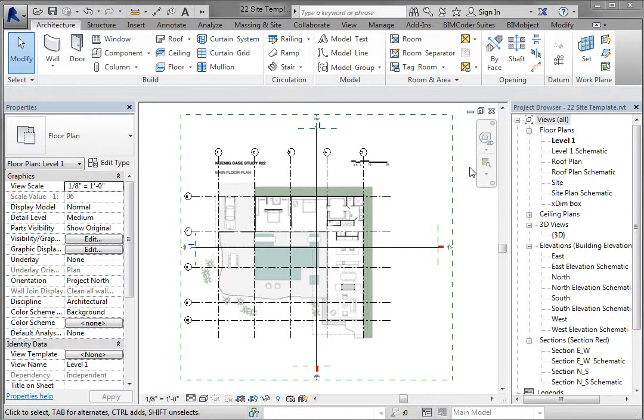Alright, so the next thing we want to do is make the floor that runs around the edge of this. What it's going to do is take whatever level 1 is, place that outline of the floor we're going to give it on that, and then extrude the floor down. Now a floor is a system family, so it only exists within a project or project template, and you can't make a floor type or floor family outside of the project. It's similar for walls and roofs and stairs and many other options within Revit.